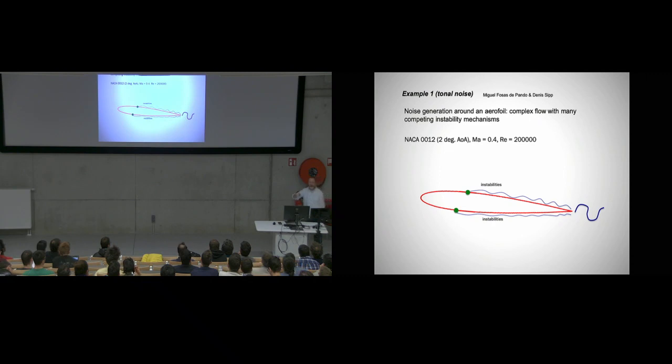And if you're a glider pilot, you actually know about tonal noise. Or wind turbines. The annoying noise that wind turbines make, that's from an instability like this. So this is how it goes. We have an instability of the boundary layer on top, and we have an instability of the boundary layer on the bottom. These two instabilities roll down and meet each other at the trailing edge, where they slam into each other, high shear.